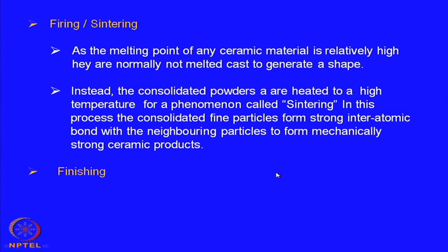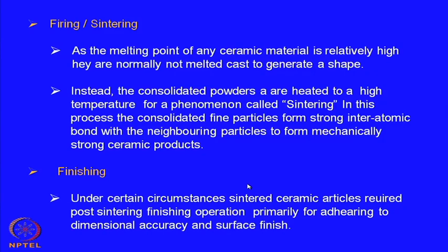Surface finish has a very important role so far as the application is concerned, and of course dimensional tolerance, because you are going through different processes, the maintenance of dimensional tolerance sometimes becomes difficult, and therefore there is a need of surface finishing or finishing of the dimensions primarily to match the dimensional requirements.